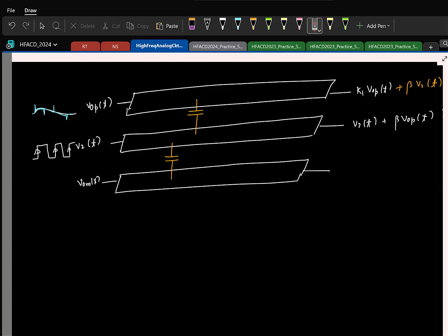Okay. So won't you try to route it like this, the middle line like this? Which one? The V2 of t perpendicular. Yeah, that's actually a very good point. If you want to avoid interference, this is the best thing you should do, right? But sometimes let us say you can't avoid it. I mean, let's say you can't help it, and to get to this point, if you route two metal lines like this, that has the least capacitance, right? So as we pointed out, if you want to minimize interference, this is what you should do. Here again, you will not have zero interference, you will have something, right?